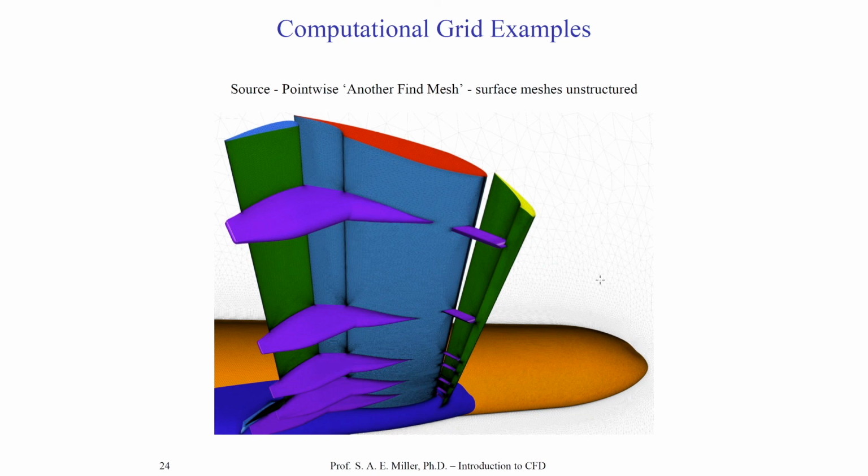This represents a symmetric plane that cuts the aircraft in half. Why do they do that? Because there's a steady flow about the aircraft which they're trying to find, and they're using a plane of symmetry of the solution, which is implied, that's being forced through a boundary condition. This will reduce the number of grid points by half and greatly reduce the computational power and time it takes to find the solution. When I see a mesh like this, I know it's high quality, and the Pointwise company makes a very high quality product with really good meshes if they have a trained user.